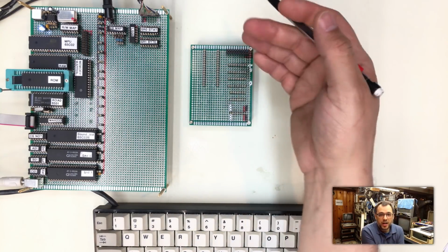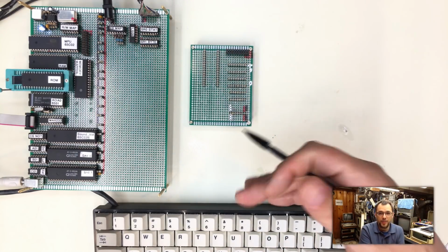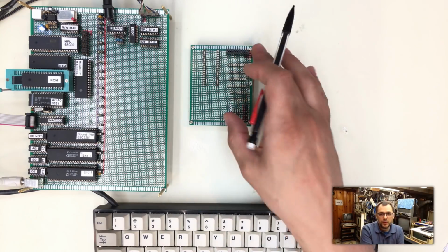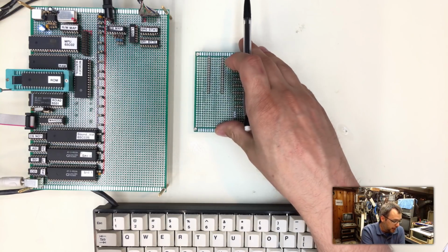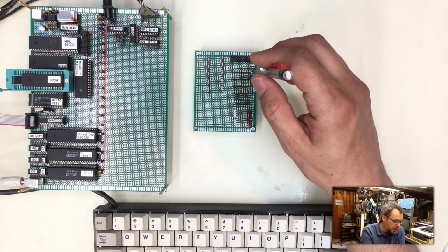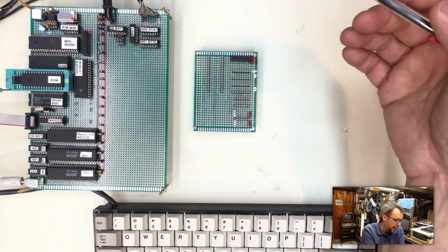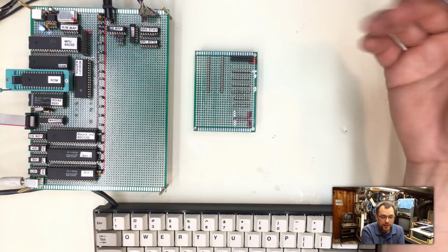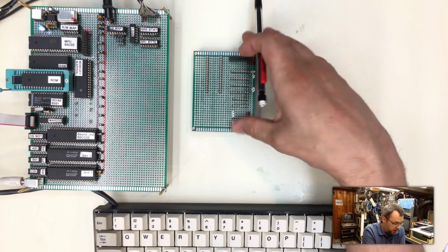Once the keyboard is designed and the interface is designed, I never have to change that again. This isn't a ROM that I'm going to be fiddling with a lot. So I thought, well, what is the simplest way I can create keyboard select logic to do that? And I came up with a way of doing that. It's effectively a combination of a 2 to 4 address selector and some diode logic to help select those lines, basically. So I was able to concatenate all of this into